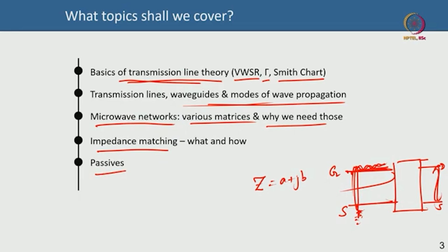And finally, we will talk about passives, and that could also be a little bit detailed. Passives are very important, because on the wafer you oftentimes need to fabricate, characterize, model and enable these passives, such as in MMIC. MMIC is a complete RF chip on wafer, on the same die, monolithically. There is no separate integration of a discrete part, everything is fabricated on the same chip. So, in that case, for instance, passives are very critical. Even otherwise passives could be very critical.